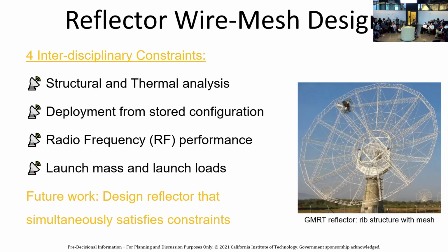It has to deploy from a stored configuration. So it is most probably going to be taken to the Moon on a rocket, and the rocket is limited to 10-meter diameter. So it has to open up from 10-meter diameter to 1 kilometer in diameter. So it has to be deployed like an origami. I'll show you some ideas.